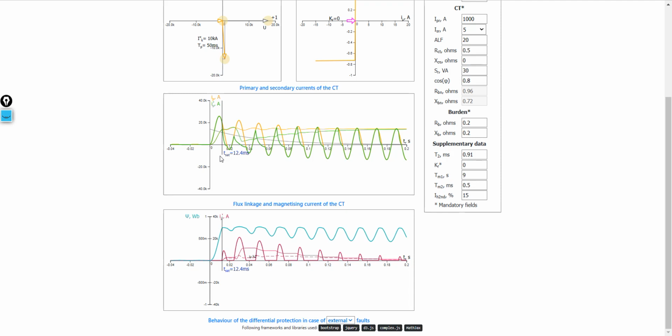The secondary current and the magnetizing current are multiplied by the transformation ratio Kr so that they can be compared with the primary current. We are going to use a dash sign for these quantities. The positive current reference system in the equivalent circuit diagram looks like this.